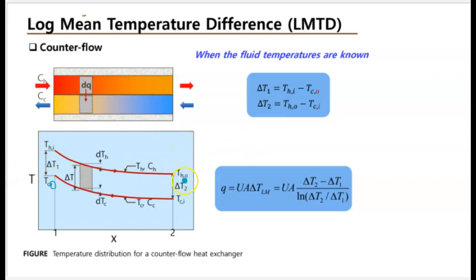On the other side, before I start, temperature, let's say here was 100 degrees, it's the hot. When it comes here, it might be like 70 degrees, because it's going to cool down. Temperature of the cold here is, let's say, 10 degrees. When it comes out on this side, maybe it's 30 degrees, rather, let's put 20 degrees, depending on the flow rate.